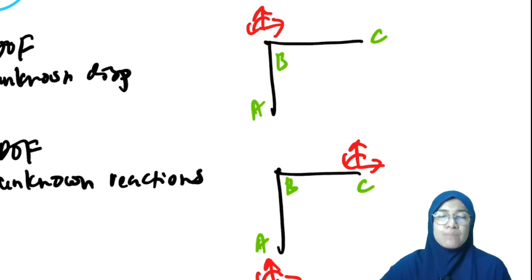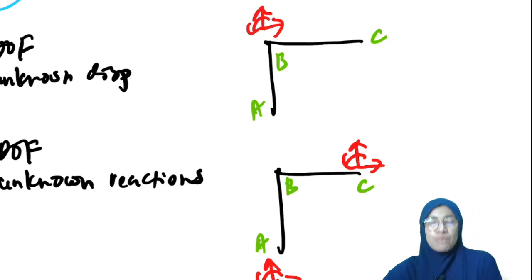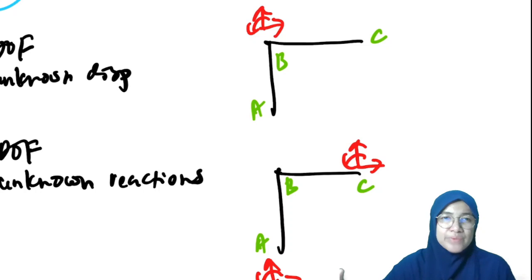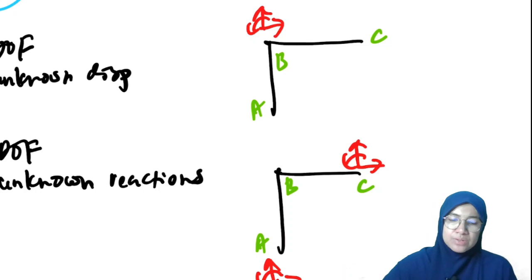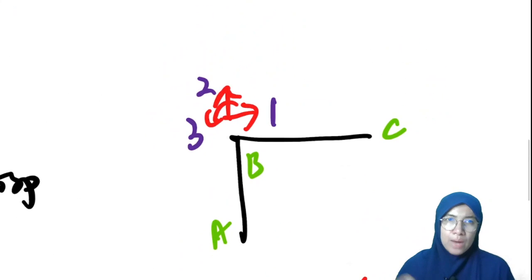The remaining must be put in the unconstrained system, representing unknown displacements. We label starting from 1 in the unconstrained system: 1, 2, and 3 at B.